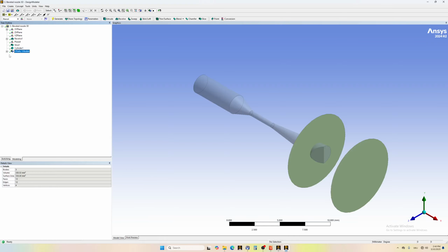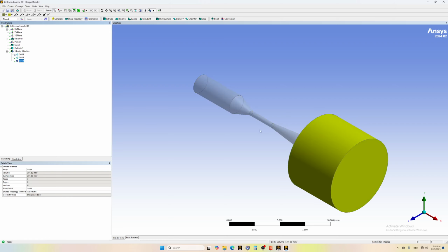So this is a very important thing. If you have multiple regions like we have now, so we have the nozzle and we have the cylinder. It's good I made this mistake, because it will be very important when you are drawing multiple regions or multiple sections. Sometimes it's necessary to do that, otherwise you cannot mesh it. So for instance, this nozzle, you can draw just this cylinder, after that this conical part, this cylinder, and this conical part, and this cylinder.